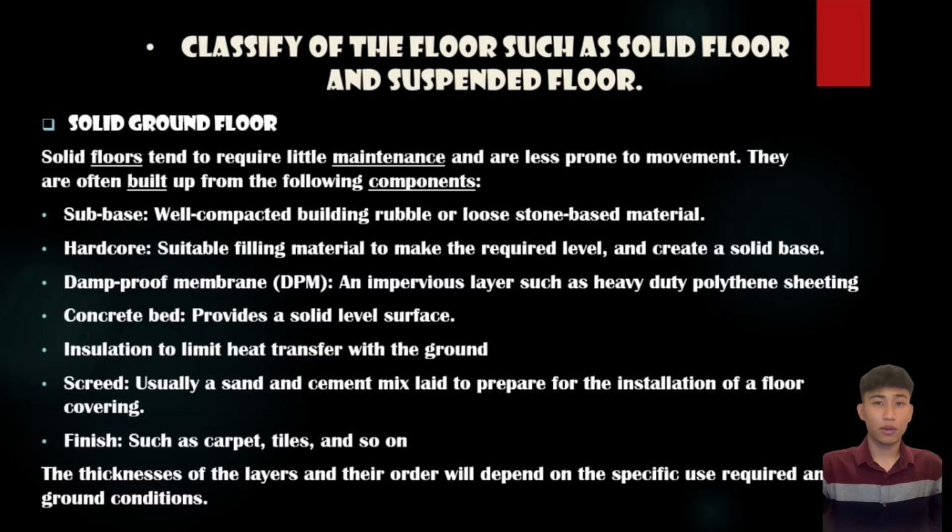Classification of the floor, such as solid floor and suspended floor. Solid ground floor. Solid floors tend to require little maintenance and are less prone to movement. They are often built up from the following components: subbase, well-compacted building rubble or loose stone-based material; hardcore, suitable filling material to make the required level and create a solid base; damp proof membrane (DPM), an impervious layer such as heavy-duty polythene sheeting; concrete bed to provide a solid level surface.